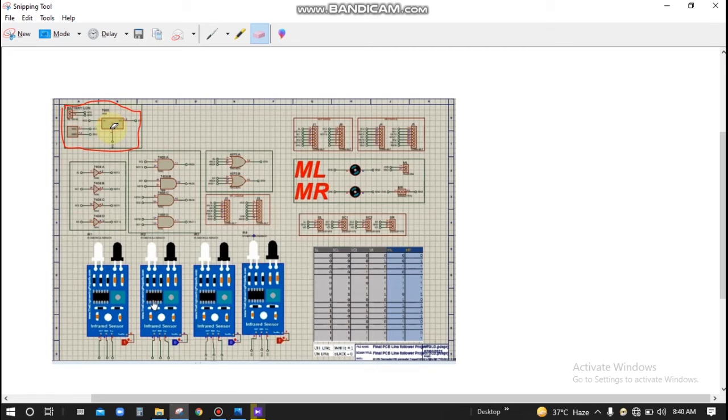This is a voltage regulator, a 5 volt voltage regulator basically. This is necessary for the ICs, so that the ICs do not burn, because the cells we have made were 7.4 plus volts. So if we give the power source directly to the ICs, they may burn.